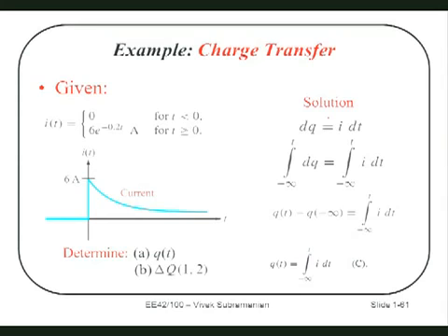Now, we're going to do two things. First, let's determine q as a function of time. This is I as a function of time. Let's determine q as a function of time. So remember our definition we had: I is equal to dq/dt. Okay? So if I wanted to find q, what would I do? Differential equations. You're going to integrate, so you're going to move that there. You're going to calculate q is equal to the integral of I dt, integrated from 0 to t to find q of t. Right? That's what we're going to do.